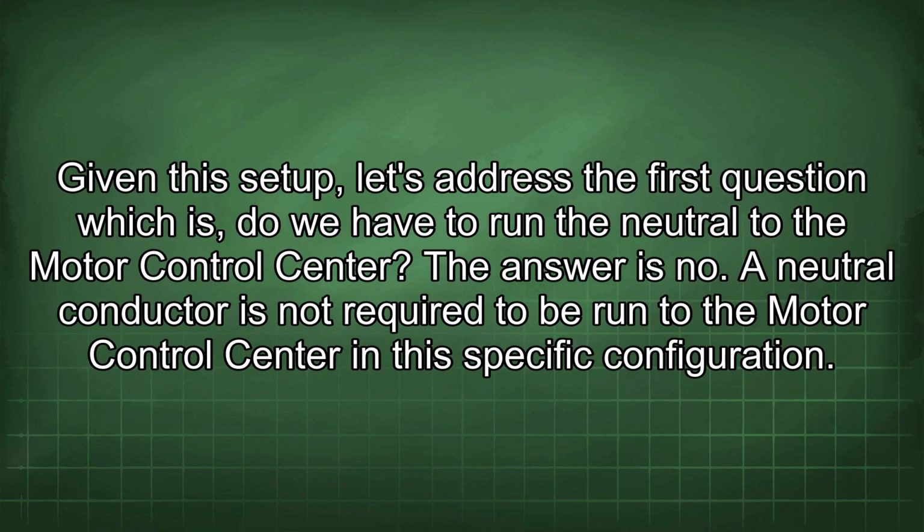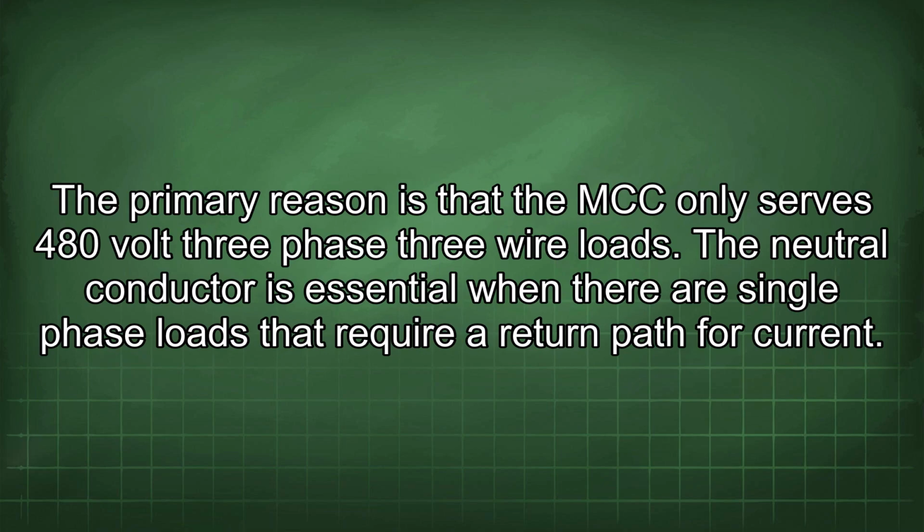Given this setup, let's address the first question, which is, do we have to run the neutral to the motor control center? The answer is no. A neutral conductor is not required to be run to the motor control center in this specific configuration. The primary reason is that the MCC only serves 480 volt 3-phase 3-wire loads. The neutral conductor is essential when there are single-phase loads that require a return path for current.